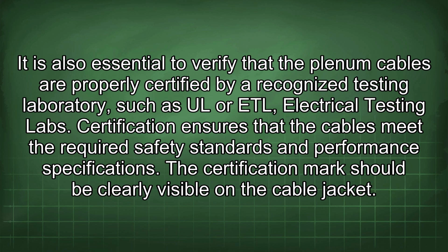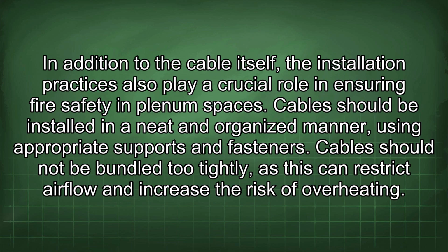The certification mark should be clearly visible on the cable jacket. In addition to the cable itself, the installation practices also play a crucial role in ensuring fire safety in plenum spaces. Cables should be installed in a neat and organized manner, using appropriate supports and fasteners.